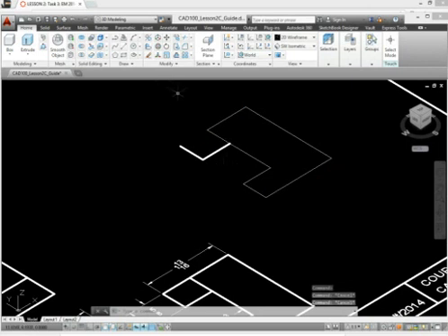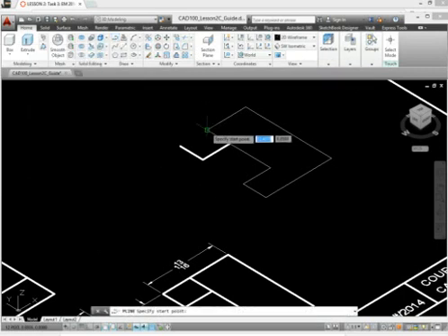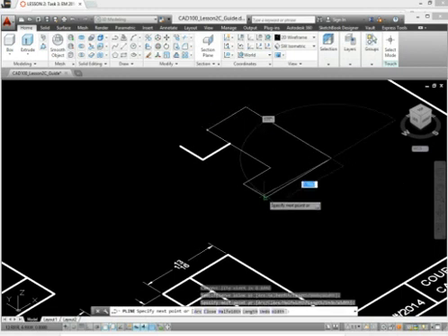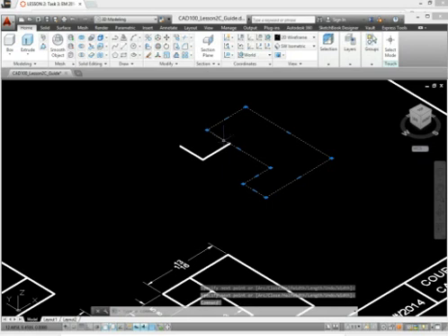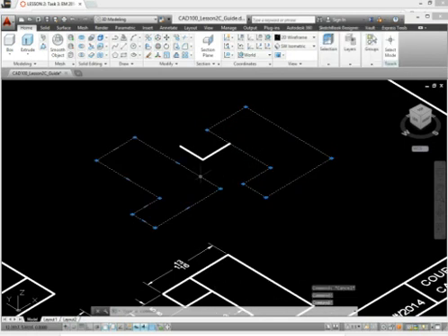The other way to make a region is a command called polyline, which is this command here. Polyline works like this. You will draw a continuous line around the path, starting at one point and just working your way around, drawing on top. And then, when you get back to where you started, hit enter. This is a polyline. Let me move it away so you can learn the difference. There's a region, there's a polyline.